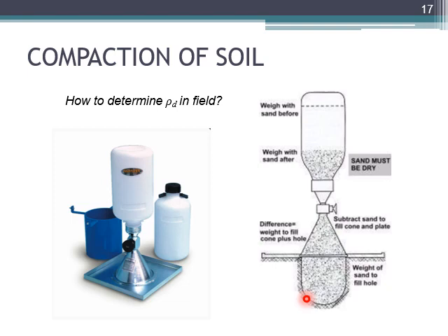So you would have to measure the volume of the hole that you have created. The easiest method to do that, if you really do have no equipment, would be to cover the hole with some plastic bag and fill it with water. Right? If you know the volume of the water that you poured into this hole, you would know what is the volume of the hole.